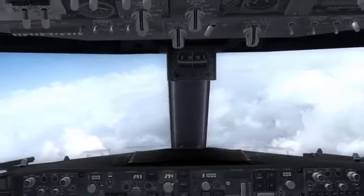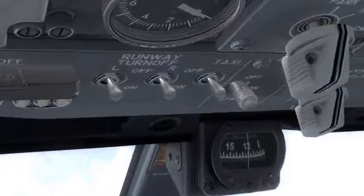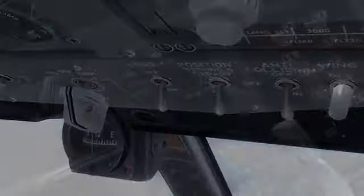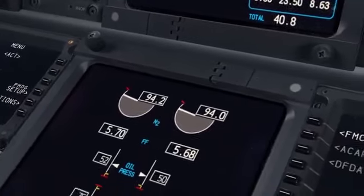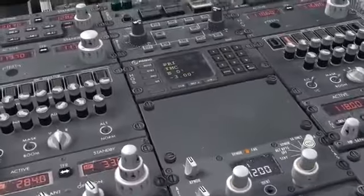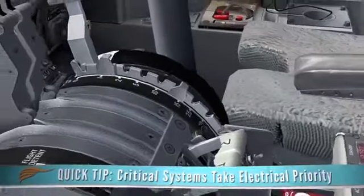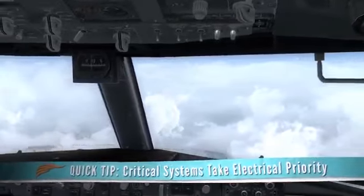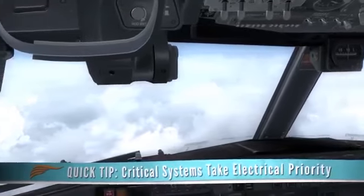Buses are essentially electric platforms from which electricity is both supplied to and drawn from by the respective aircraft systems. Each electric current type has a respective set of buses for both essential and non-essential items. The whole purpose of buses is to allow essential items to still remain powered if there was an electric power shortage or emergency. During an electrical emergency, it is far more important to have an active, functional communication radio as opposed to having functional strobe lights. For this purpose, both items draw current from different electrical buses.